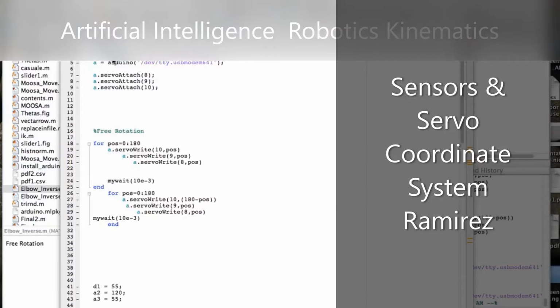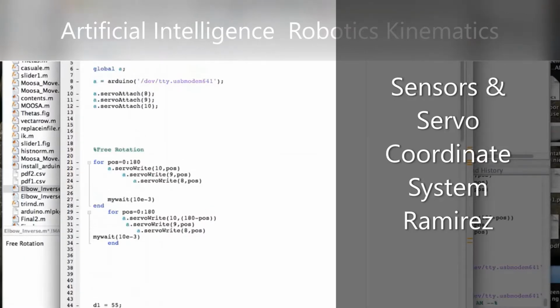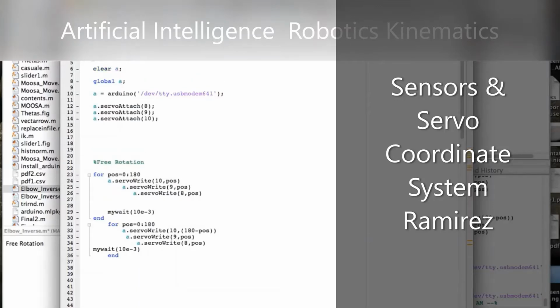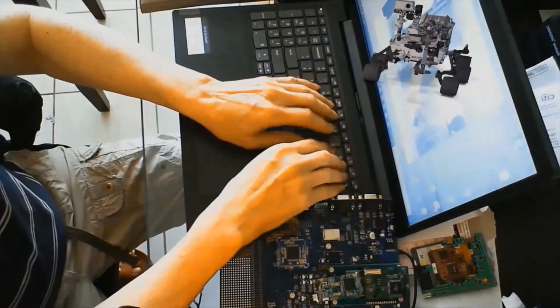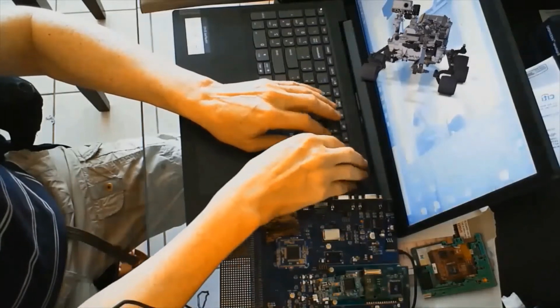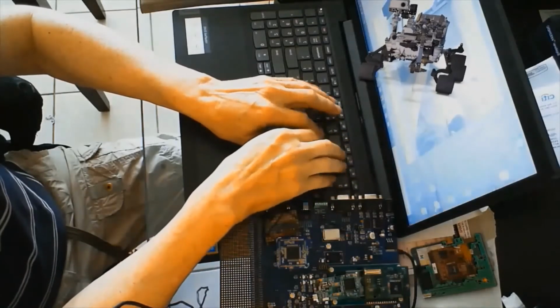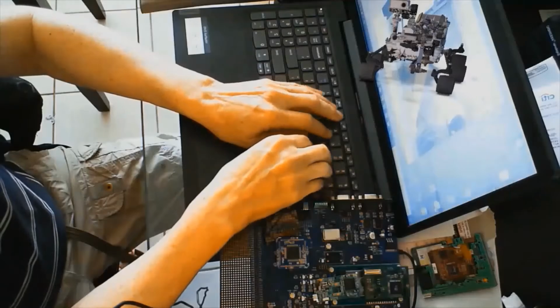The relationship between the tool velocity given in the sensor coordinate system and the joint speeds. The reference velocity of the tool is obtained by detecting the deviation between the target and the actual positions of the arm with the sensor.